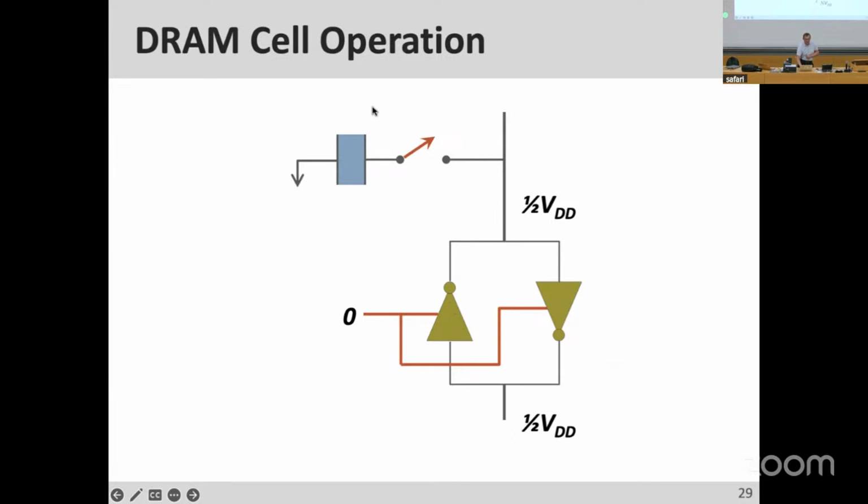So basically, these are what we have seen earlier. This is a word line. I'm showing you only one cell over here. But this is the access transistor that's connected to a word line, which is not exactly shown here. The control over here is the word line. We will see that later on. And then this is the bit line. So I'm showing you one cell, but you can imagine a two-dimensional array of cells, a grid, that we're going to build soon on top of this.